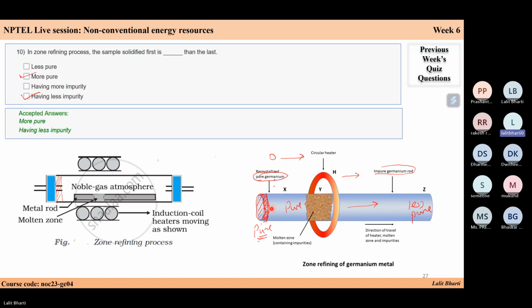So what we are doing here is similar to your float zone technique. By using this heating coil, we are heating this area, and let's say you have a pure seed here. So we are aligning the amorphous germanium along with the seed's crystal structure, and we are making a pure type of germanium, or let's say semiconductor.